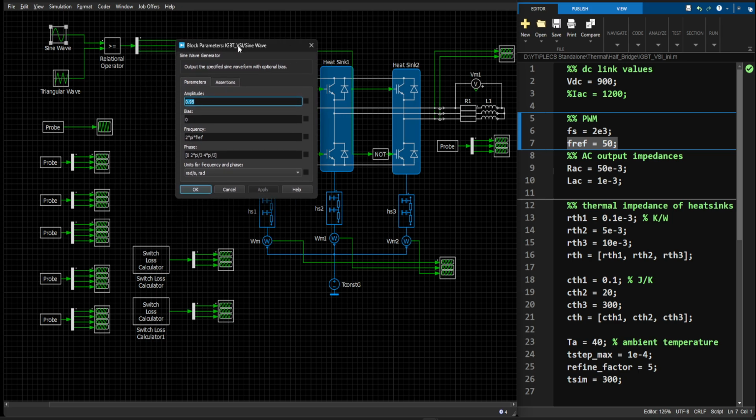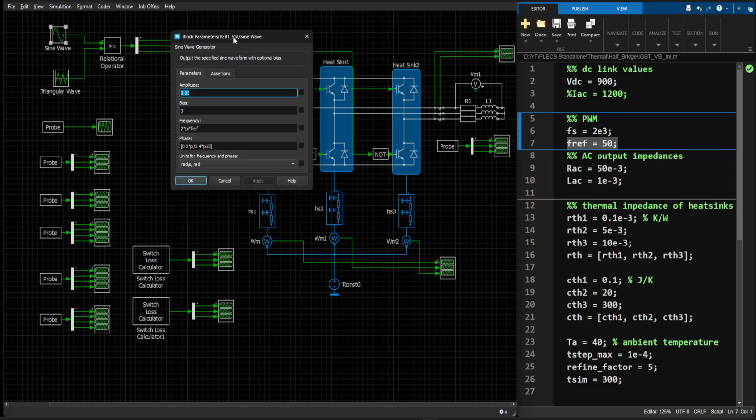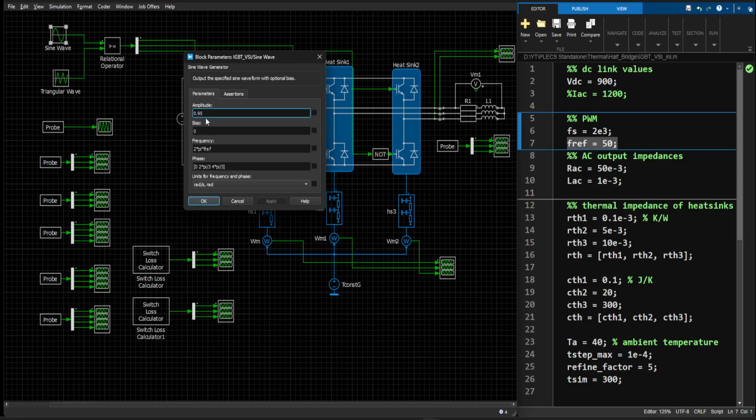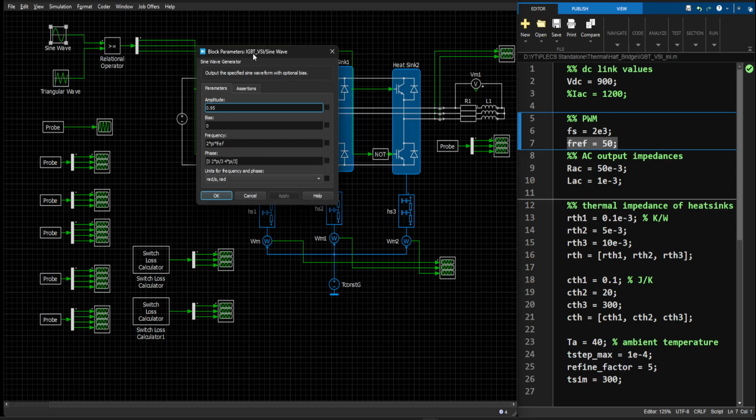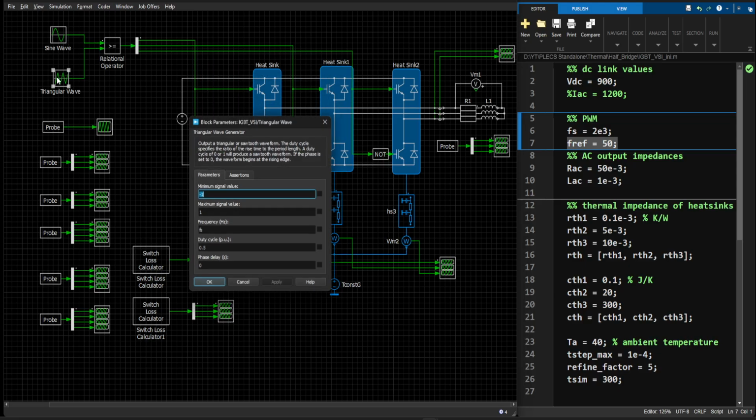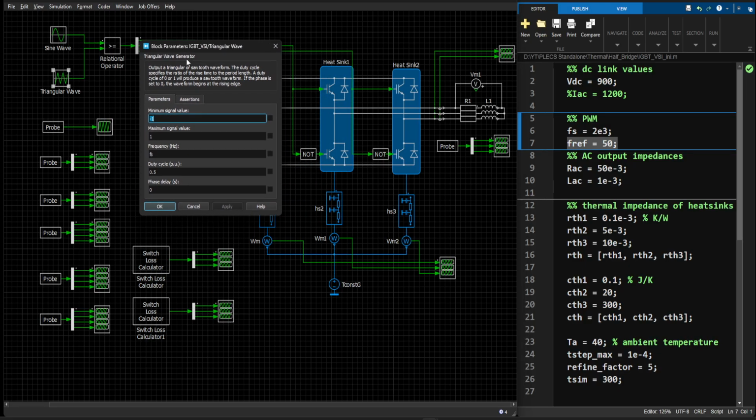You can also watch one of my previous videos in the inverter sections where we went into detail about the modulation techniques. Principally, I have taken a modulation index of 95%, and we have 3 signals generated inside one sine block, all 120-degree phase shifted. And we have the modulator signal, which is the triangular wave, with amplitude between ±1.